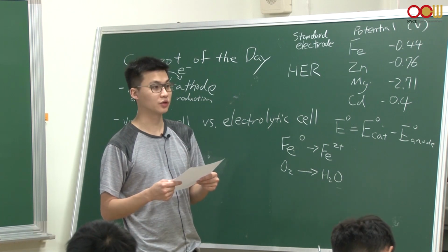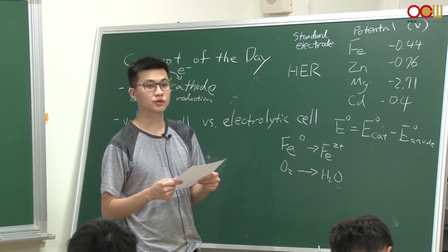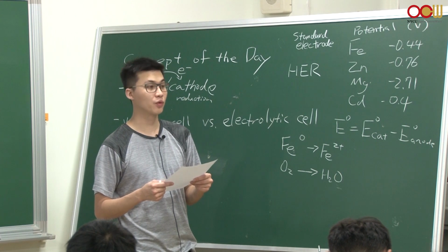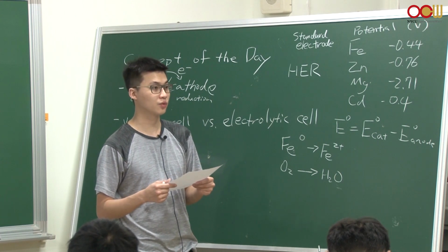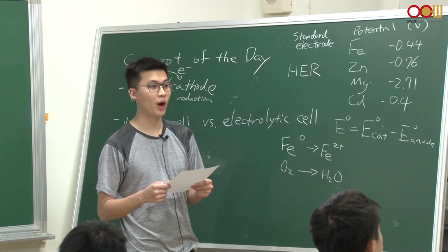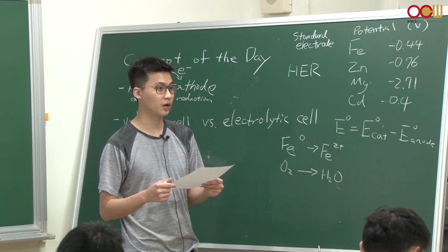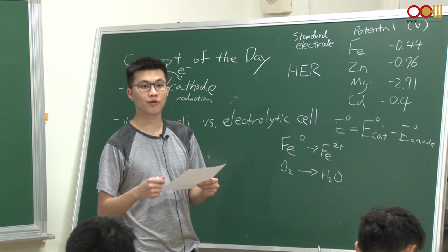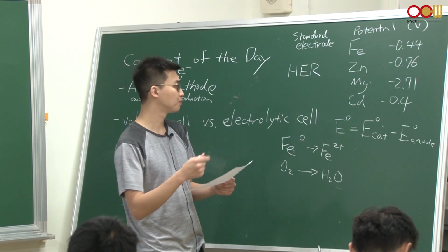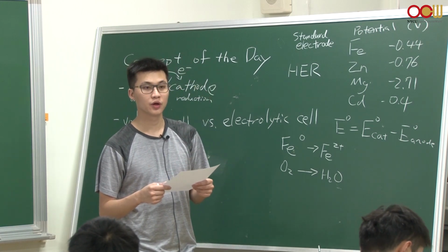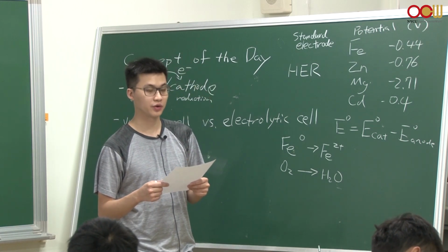There's a lot of salt, right? Salt is known to accelerate such a process because we're thinking about a redox process. In pure water, the conductivity is quite low. In salt water, the solution becomes more conductive when you have more salt in it. So in the presence of a high ionic strength solution, the rate of the rusting process will increase.